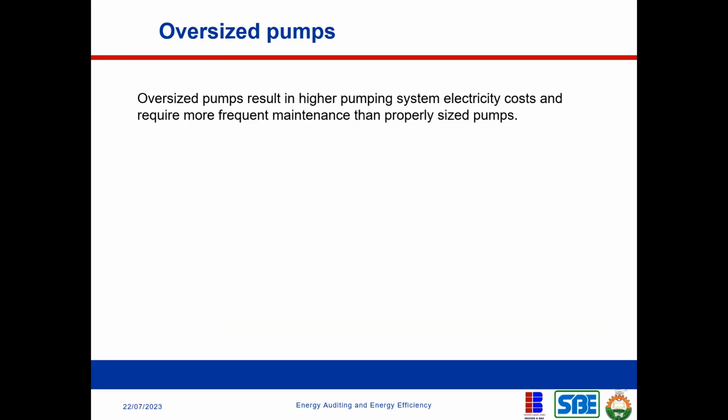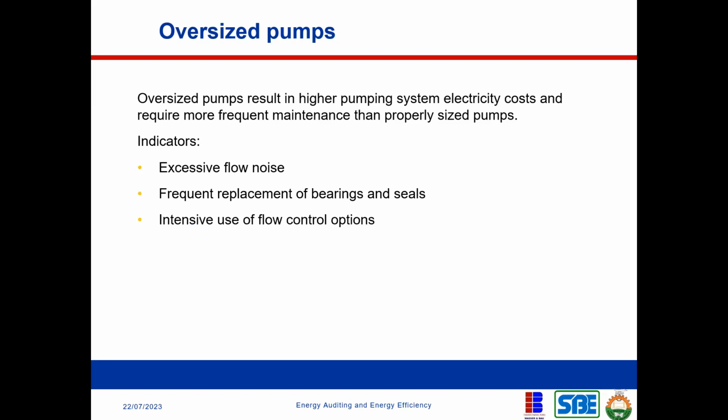Sometimes you might oversize your pump, which is not a good thing. If you go for an energy audit, look out for areas where a pump has been oversized. And how do you know when a pump is oversized? You see excessive flow noise, and you have frequent replacement of the bearing. So you can ask questions to get an indication of when the pump is oversized.